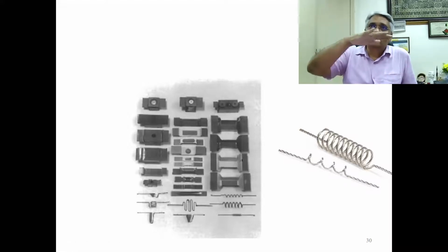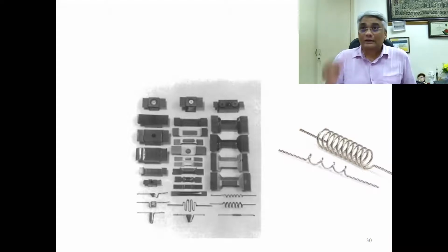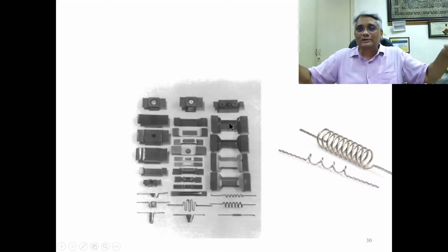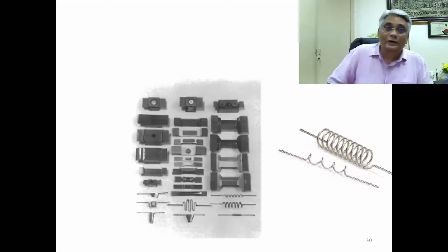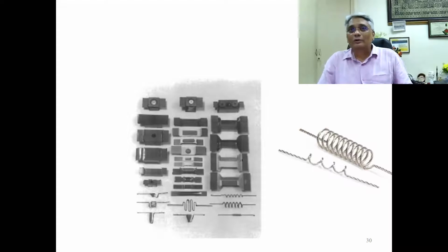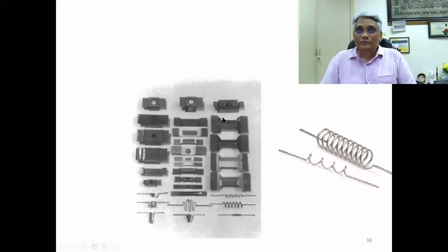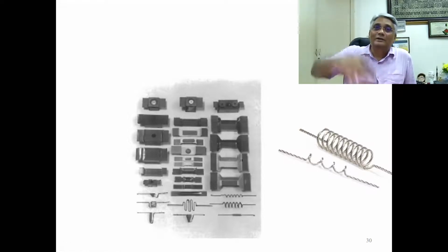especially if I want to make gold contacts, right, which are required for some experiments. I can only afford to use a small piece of gold to be melted. So I don't want to use a large boat like this, in which once gold melts, it spreads all over. So you end up evaporating some of the gold, but then most of the gold remains as a coating on top of the molybdenum sheet itself, if you're not completely evaporating the gold also.